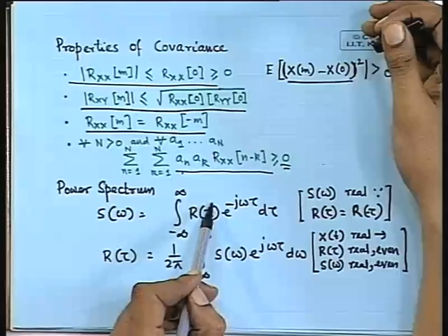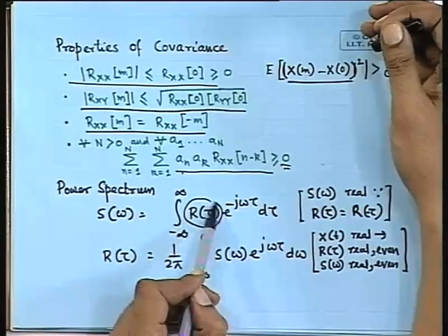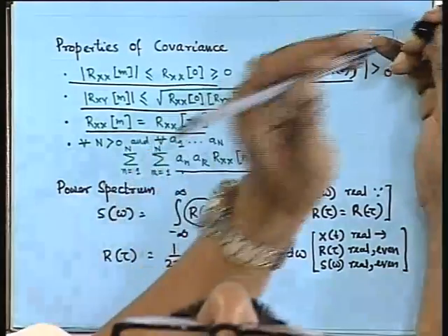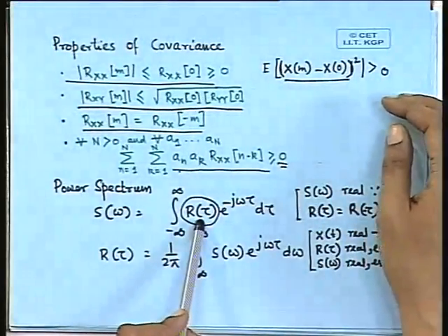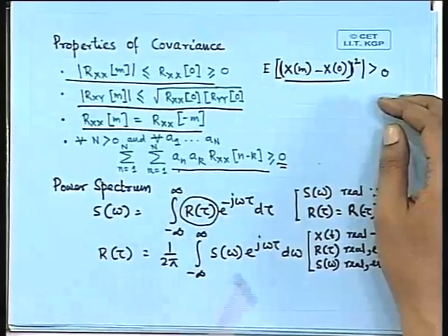We realize that after you have taken the autocorrelation function, it has now become a function of tau. So if it is a function of tau, we can always take its Fourier transform. Any function f(t), under the regularity conditions that this integral will actually converge, will have a Fourier transform. So now the question is: what will happen if we define a Fourier transform of an autocorrelation function?